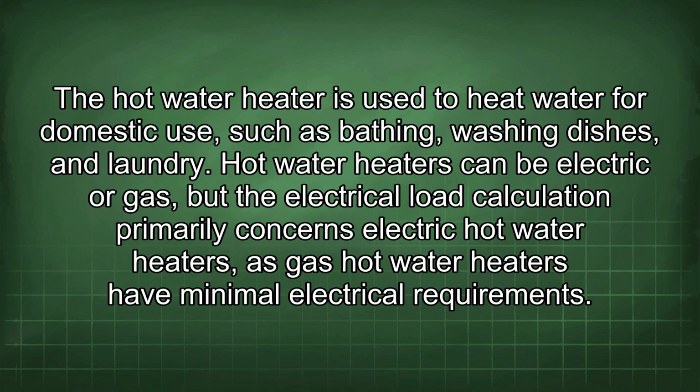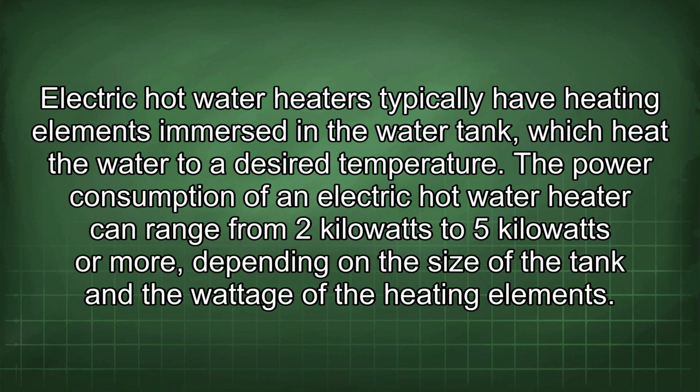The hot water heater is used to heat water for domestic use, such as bathing, washing dishes, and laundry. Hot water heaters can be electric or gas, but the electrical load calculation primarily concerns electric hot water heaters, as gas hot water heaters have minimal electrical requirements. Electric hot water heaters typically have heating elements immersed in the water tank, which heat the water to a desired temperature. The power consumption of an electric hot water heater can range from 2 kilowatts to 5 kilowatts or more, depending on the size of the tank and the wattage of the heating elements.